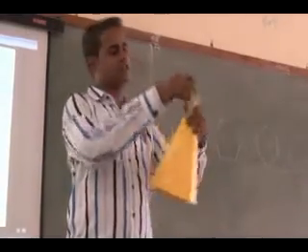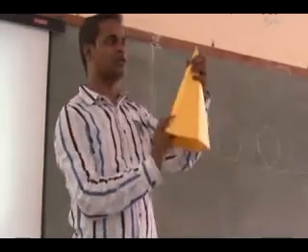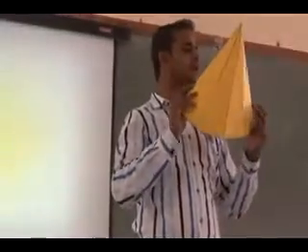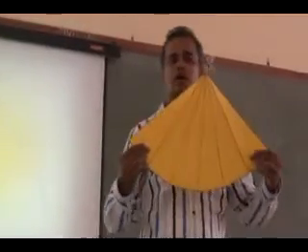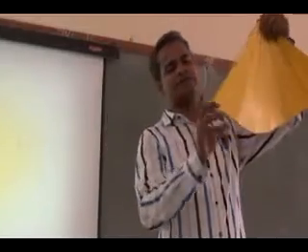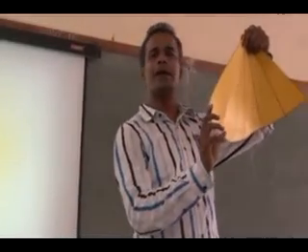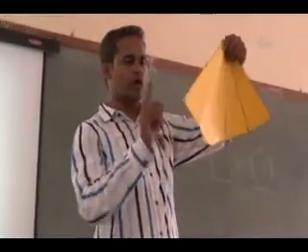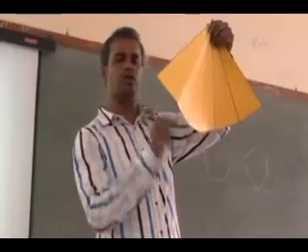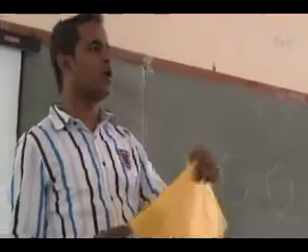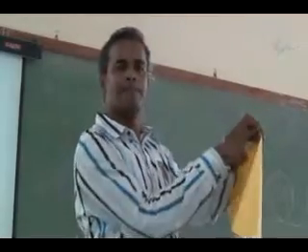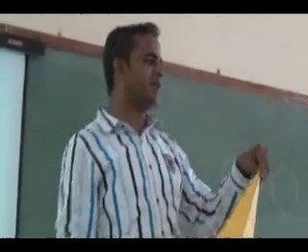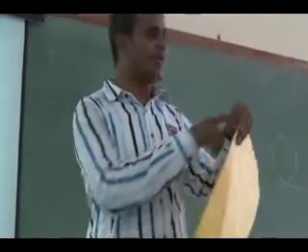I can cut this along a slanted location and unfold it so that I can get a development of the pyramid. Okay. So what will this length be? It will be the base side. Okay. So how can I obtain these corners? I have to join them with a straight line. So how will I develop this? What is this length? Slant edge length. Okay.